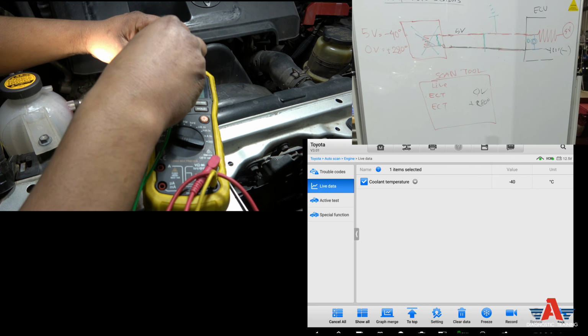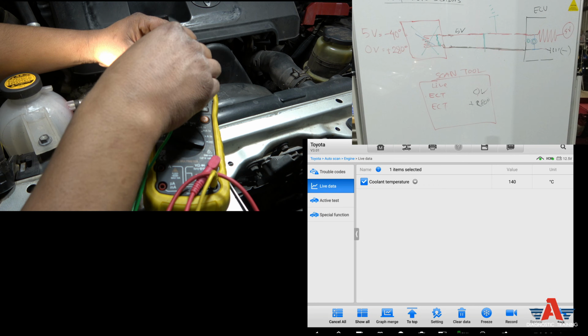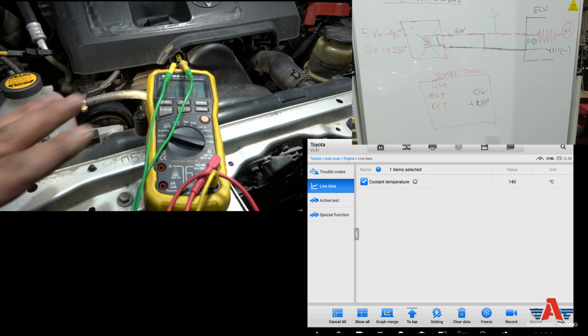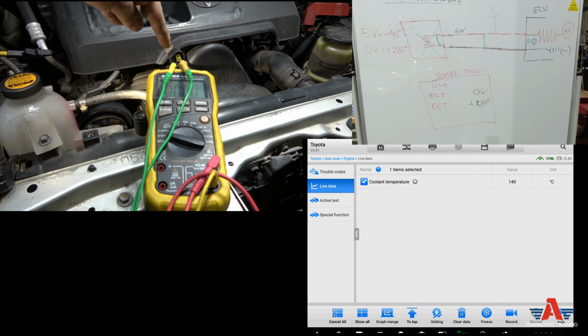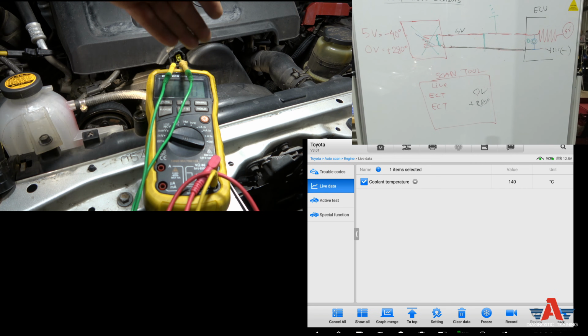Guys, I'm trying not to damage those terminals. Okay, I hope I'm still shorted. Now, if the sensor is bad and has a short inside, when this plug is plugged into the sensor, isn't that the same thing as me giving a jumper here? Isn't it the same thing?